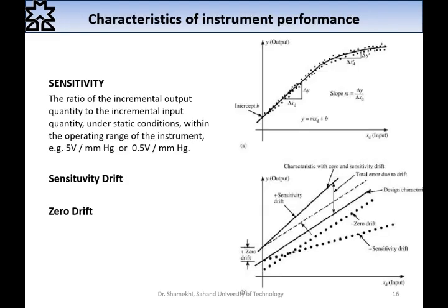Sensitivity is another important static characteristic. The sensitivity is the ratio of the incremental output quantity to the incremental input quantity under static conditions within the operating range of the instrument. All these words are important.